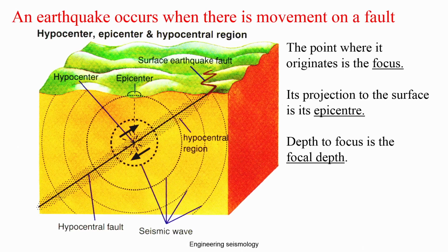Okay. So, if you talk about the location with respect to a particular place, then you can bring in the concept of hypocenter or hypocentral distance. For example, I have a house or station here. This is my focus point or the hypocenter, this is the epicenter. This distance is the epicentral distance, and this distance is the hypocentral distance. This is D, this is HD, and this is the depth of the earthquake. Okay. So, these are all the waves, how the seismic waves get generated and propagate in the typical earth sections.